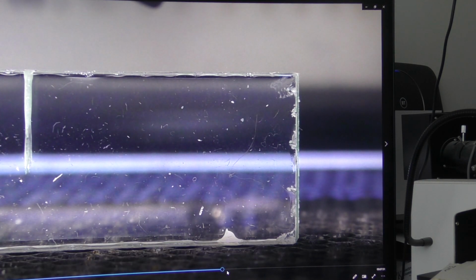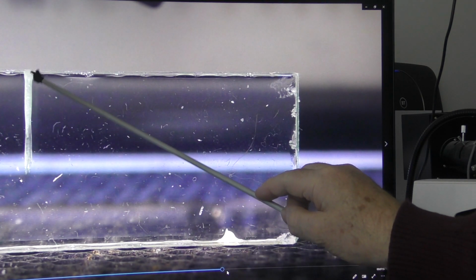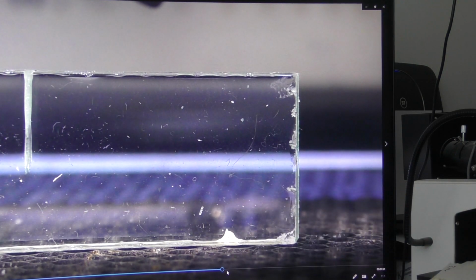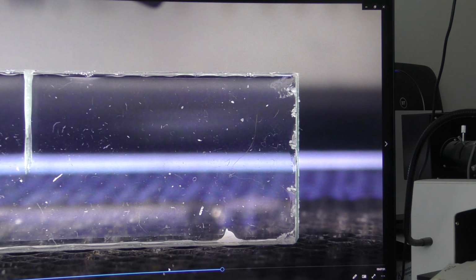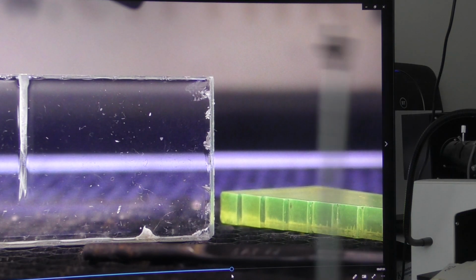Oops, it's bigger. Okay, now that was with the lens set correctly at the focal point, 25.4 on the surface. I then did a little bit of experimentation, but this time instead of 25.4 it was 24.5. In other words, I had actually pushed the focal point into the material by roughly a millimetre.